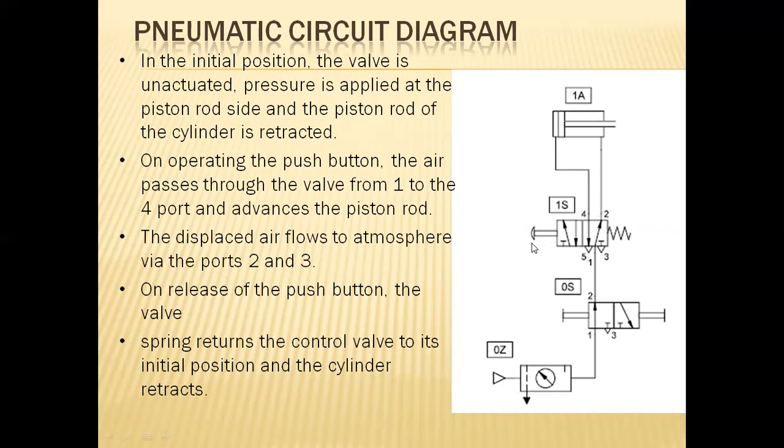So here DC refers to directional control valves, and this is a symbolic representation of the FRL unit. Here the filtration process is taking place, here the regulation process is taking place, and this is the lubrication process. So this FRL we have almost discussed. Here this is a symbolic representation of compressed air supply to the system. The system refers to the movement of this cylinder to the forward stroke and towards the return stroke. And here we'll be discussing from the starting onwards. This is the origin point.